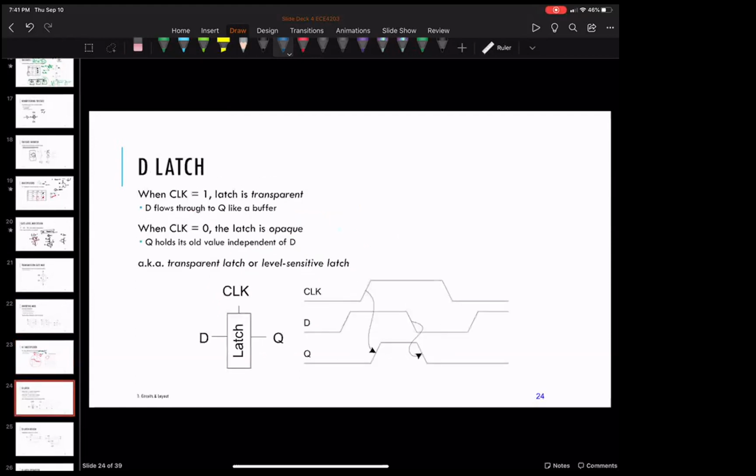An example of that is a latch. The idea for a latch is that if the input is a certain value, it doesn't pass to the output until the clock arrives. Now there's a concept of time because there's a concept of a clock. D could do anything here until the clock arrives. It could be 0, it could be 1, whatever.